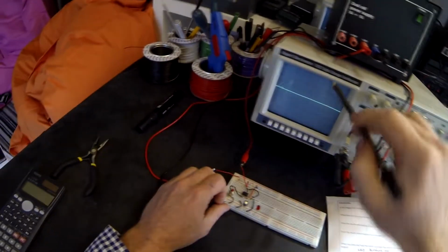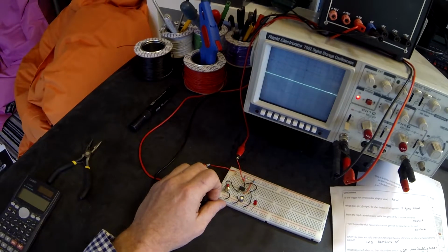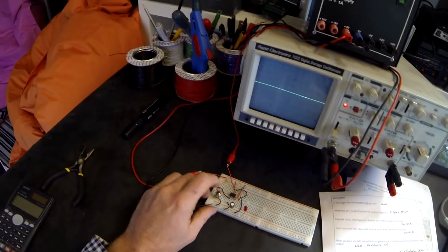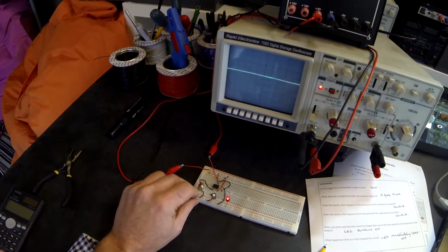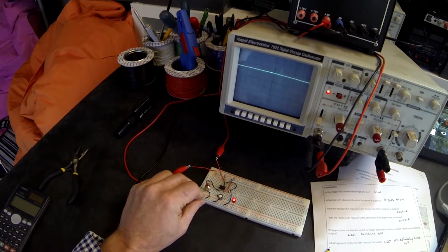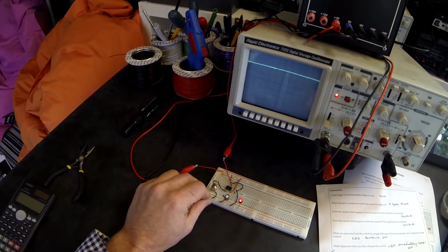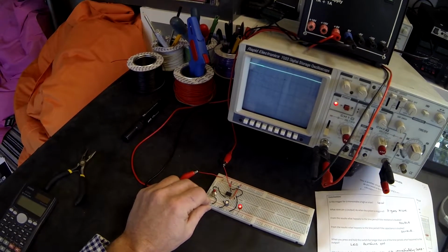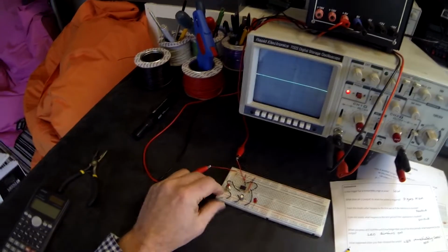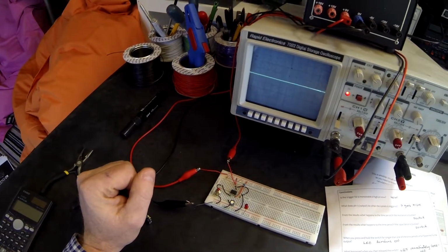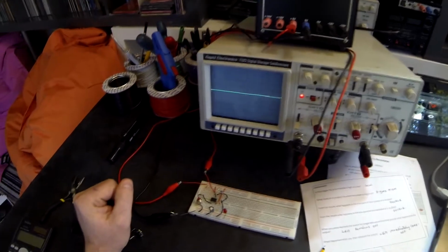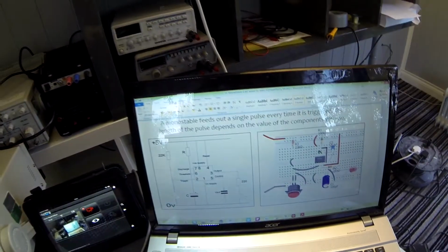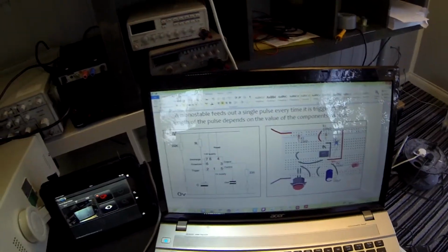And you saw the voltage immediately discharge on pin 6 and pin 7 because they're connected together, and the LED went off. I'll do that one more time. Starting to charge, 1 volt, 2 volts, LED still on, 2.8, 3, 3.2, 3.4, there we go, 3.4 volts. That is how the 555 manages to charge and discharge at very precise levels. This is the end of activity 1.